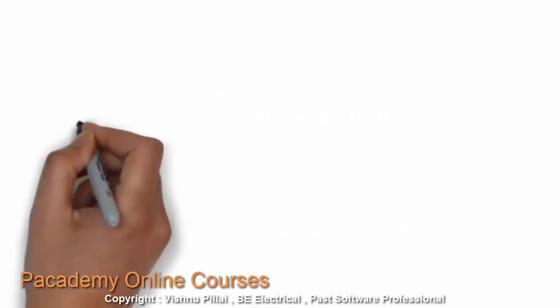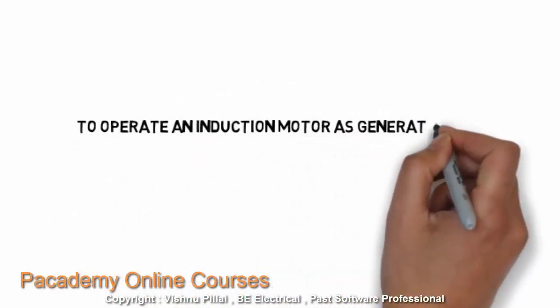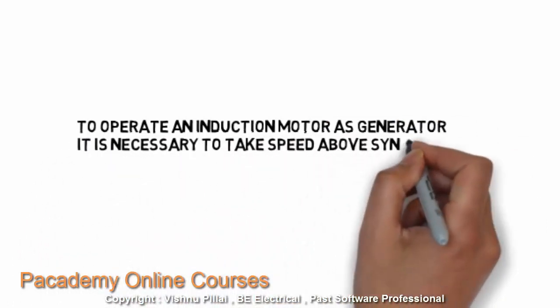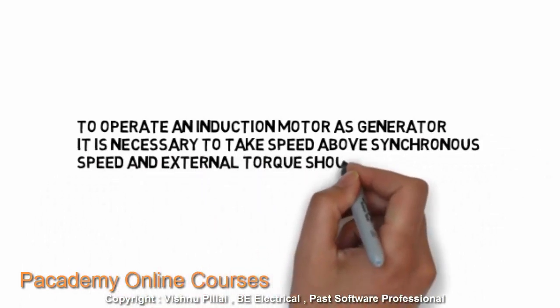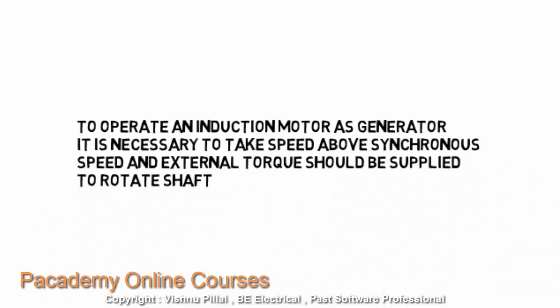This region is known as the generating region or the generating mode, and it can be used very efficiently to convert asynchronous sources of mechanical energy like wind turbines and water turbines with uncontrolled or non-regulated flow. This will cause the prime mover speed to vary with time or not be very constant, and such machines can be used to convert into electrical power by using an induction motor.